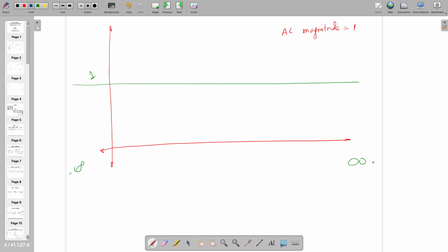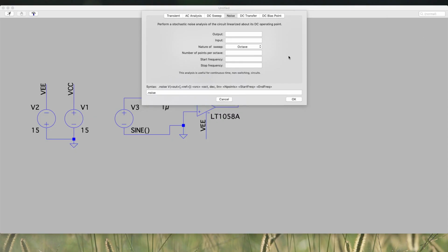So that is what noise is, and these are basically known as device noise, what I told, thermal noise, or some noise are highly stochastic and you cannot predict them. Those noises are like popcorn noise, so they are bursting and they are also known as burst noise. So those are going to distract your signal.